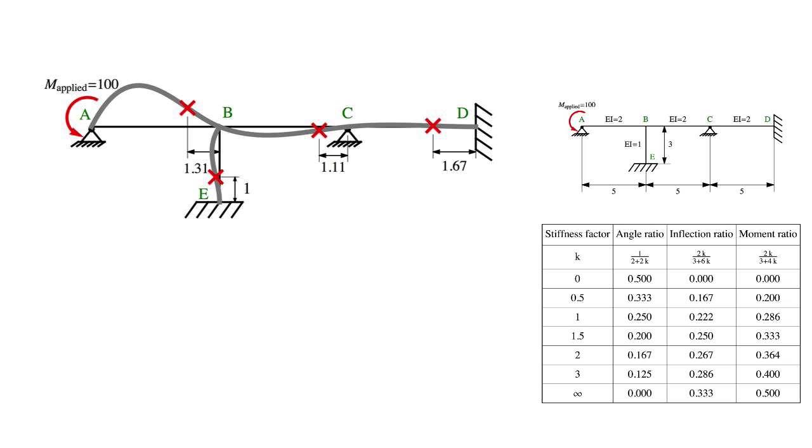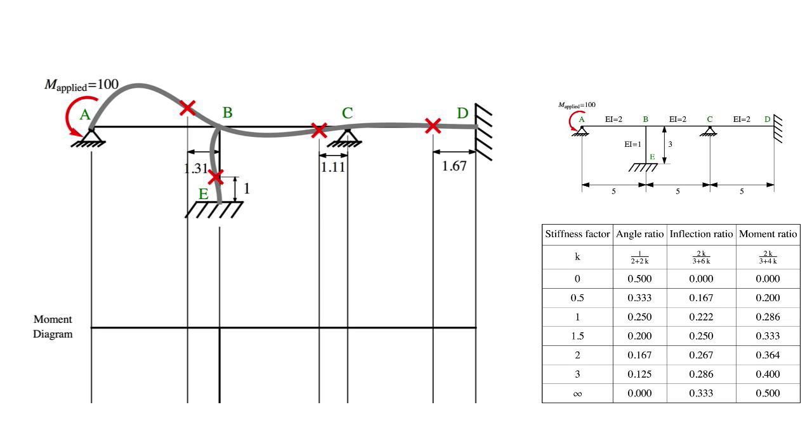of all inflection points. Next, let's sketch the bending moment diagram. We will draw it on a separate reference figure under the deformed shape. We extend lines from all the nodes or joints and also from all the inflection points. This is useful because the bending moments must be 0 at all inflection point locations, and we can mark those values right away. We start with a loaded member, which is beam AB.